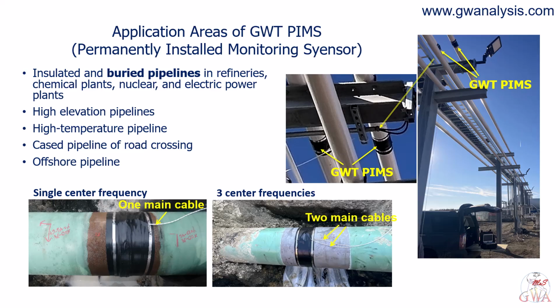A single frequency measurement on a pipeline tells you about the defects that frequency happens to be sensitive to. It does not tell you the pipe is clean. When you install a permanent sensor, you are choosing what that line will be able to tell you for the next 10 years. Choose the installation that can operate at more than one frequency.